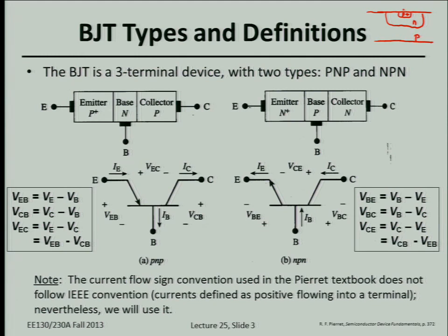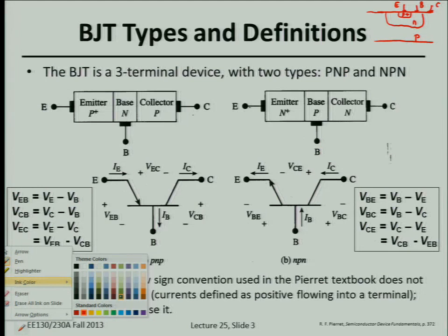Okay, so then we have metal contacts at the top surface, right? Basically, when you make an integrated circuit, you have metal contacts coming down to the surface of the silicon to connect the 3 terminals of the transistor. So we have usually a structure like this, a collector, the base, and the emitter contacts all coming from the top side. But you can see that the structure is not symmetric between the emitter and collector, geometrically as well as doping-wise.